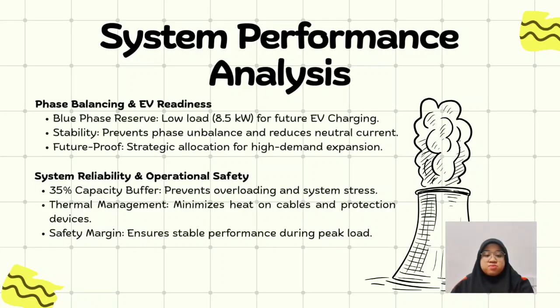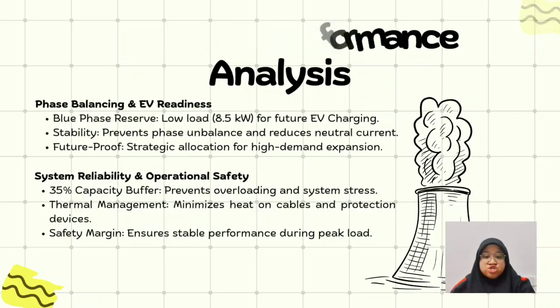Second is system reliability and operational safety. The second point is regarding our 35% spare capacity. By not running the system at its maximum limit, we reduce heat stress on cable and protective devices. This improves energy efficiency and significantly extends the overall lifespan of the electrical installation.